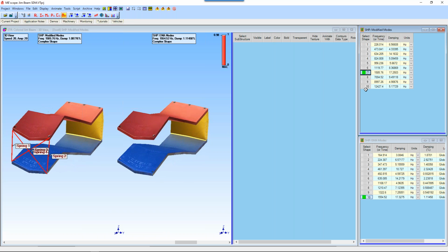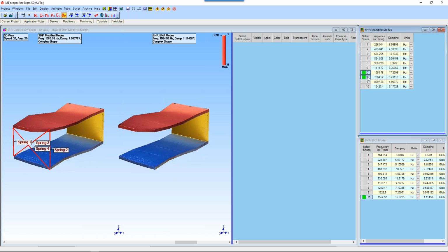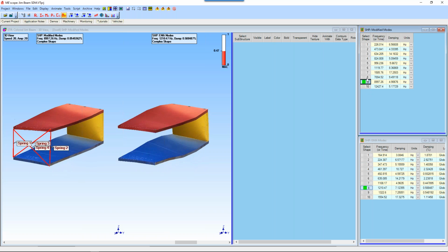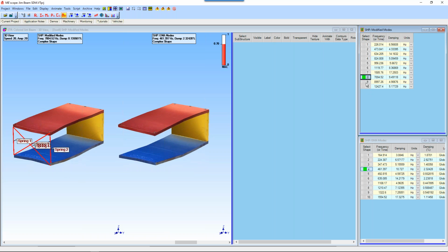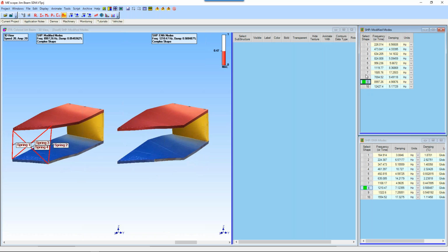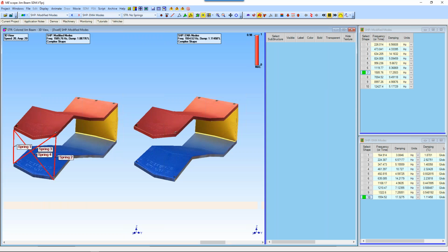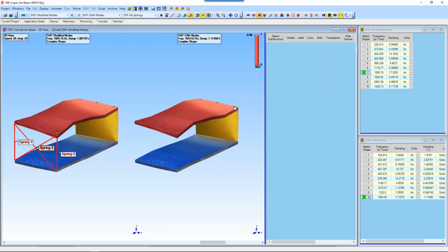But you can see because of this truncated model, I've got 3 computational modes in here now. And I can just tell that by looking at their mode shapes that they are not showing the effects of the spring. But the one at 1500, that correlates well with the unmodified structure.